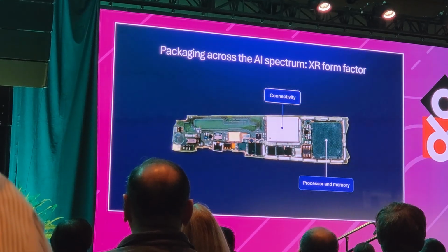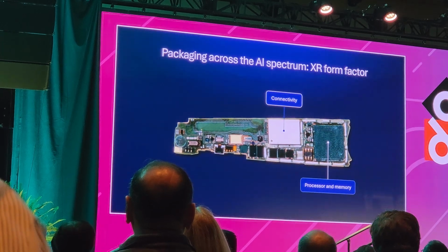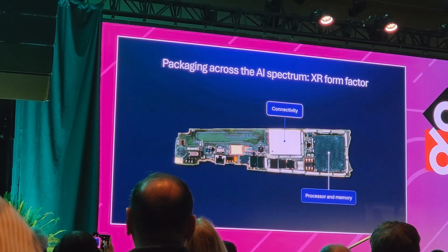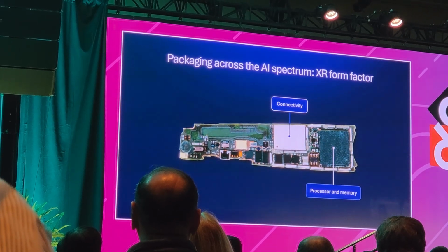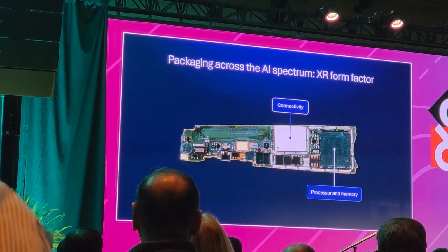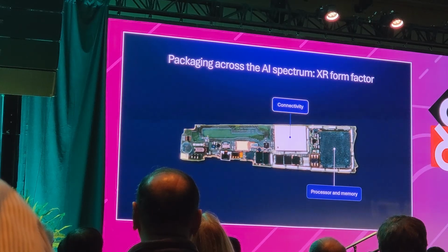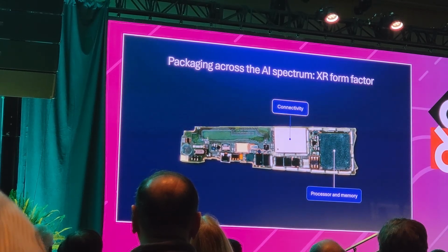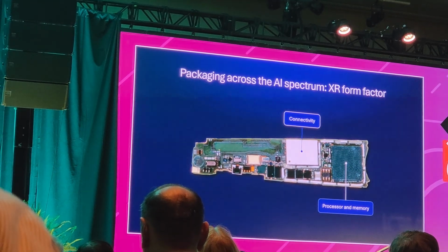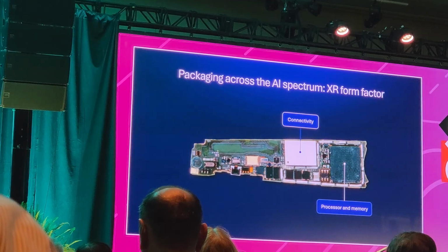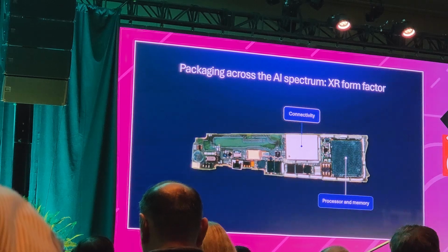Another area, for glasses, for example. The arms of the glasses are very thin, and we don't want to make those any thicker because you want a slick and stylish product so you get high adoption. So you don't have a lot of space to work with. The SoC, as well as thermal and power characteristics, will be much tighter than mobile, for example. So even if it's economically viable and technically possible to integrate into a single silicon, we don't want to do that because you might want to split the system into multiple die so you can use the whole space on the arms of the glasses.